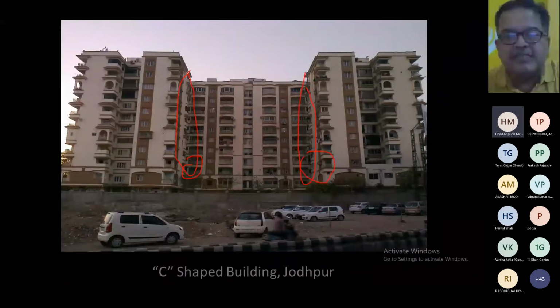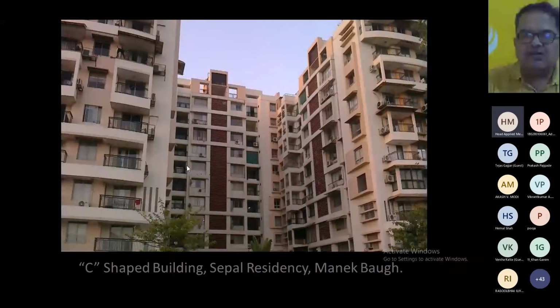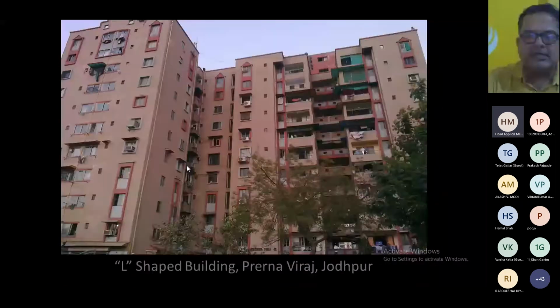It was a C type of building, and because of the C shape, the re-entrant corner is highly stressed, and one portion of that C type building collapsed. Right. Again, you see such kinds of structures in metro cities.